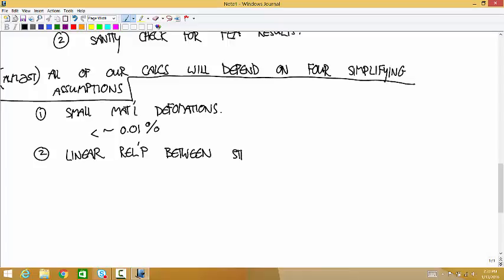Can you think of a mechanical relationship you've seen, where the relationship between the load and the deformation is linear? A spring. Yep. We're going to deal with it in more than one dimension, but this is going to be a 3-dimensional version of Hooke's law.